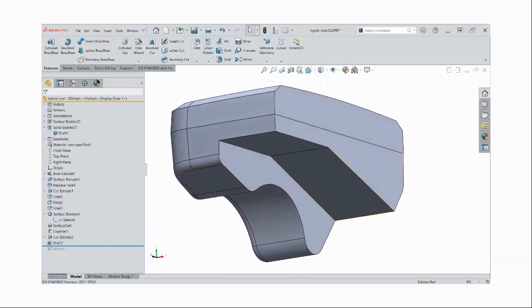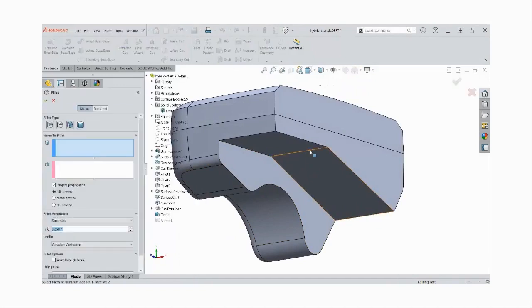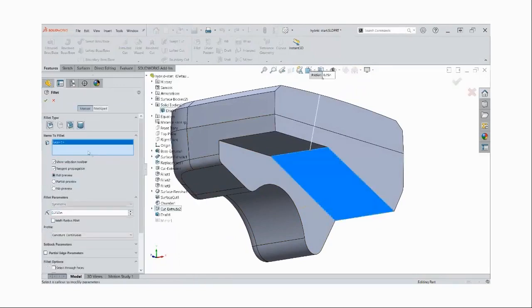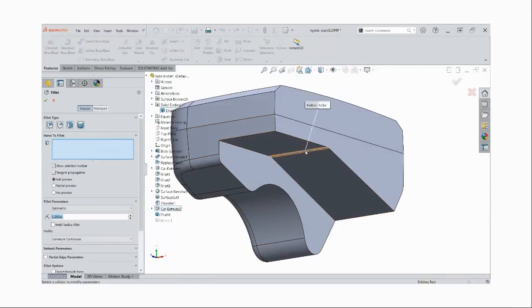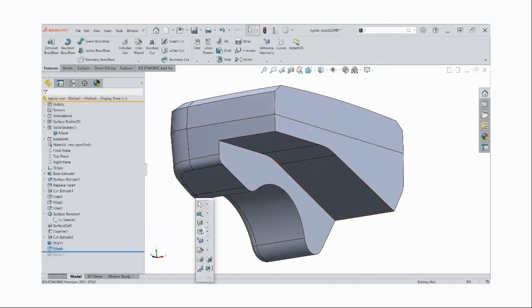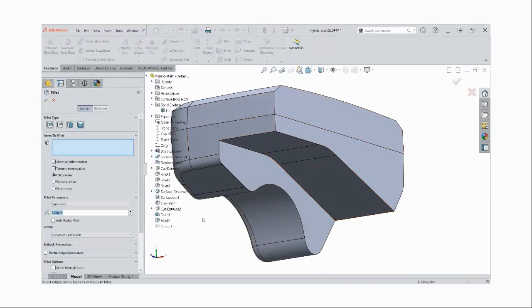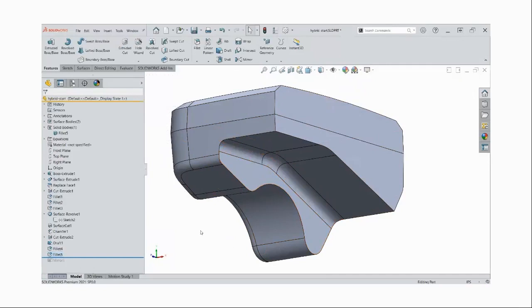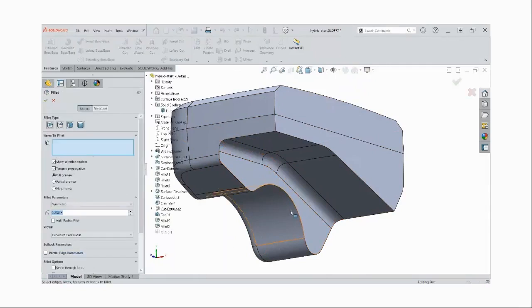And then, as you can expect, we'll be doing the second round of fillets here. So just give me a moment to get through that. Pretty much, on a product like this at least, I wouldn't expect there to be hardly any sharp corners. So again, starting with the biggest fillets first, usually. And then just kind of being intelligent about the way I apply the sequential fillets, so I end up with one nice loop at the end. So this last selection is going to go all the way around.